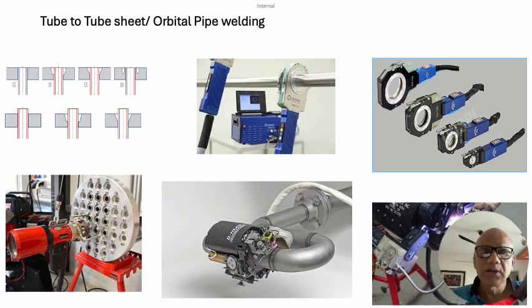a kind of TIG torch holder. That means a socket where you put your tungsten, and the entire thing, the collets are required to suit the diameter, and the collet completely closes any gap between the pipe OD and the chamber, and the gas is purged into it with very beautiful controls, which has 999 sectors, and for every sector you can have a separate program. Similarly in this orbital welder for tube to tube sheet and this tube to tube or pipe to pipe welder.